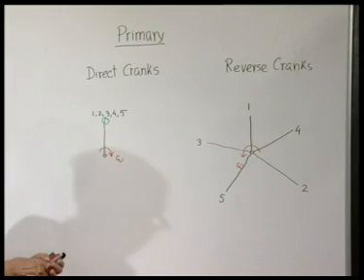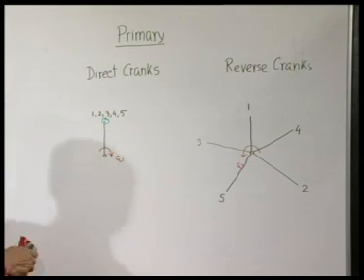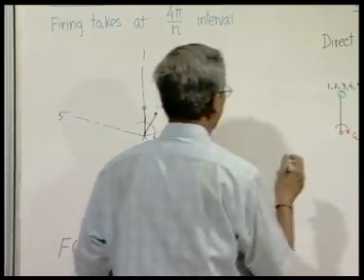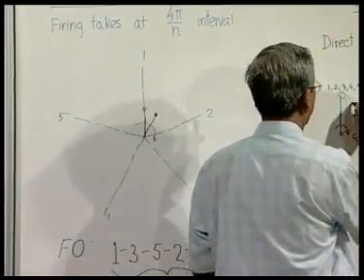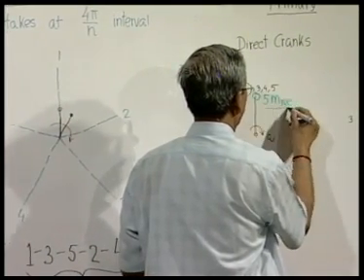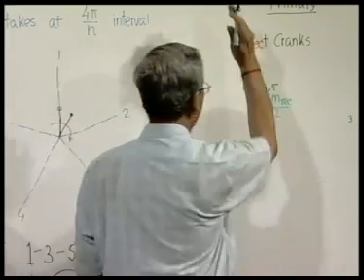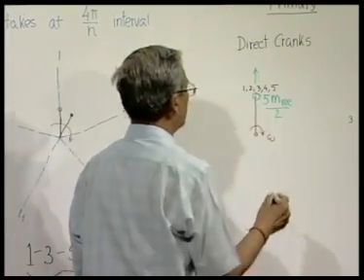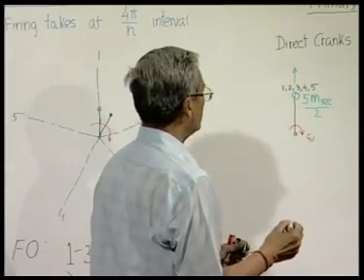So, these are the reverse cranks, they are all rotating in the opposite direction at the same speed omega. Now, if we place them, how much mass we have to keep will be m reciprocating by 2. So, 5 of them, so it will be 5 m reciprocating by 2. So, the centrifugal force produced in this direction will be 5 m reciprocating omega square r by 2.